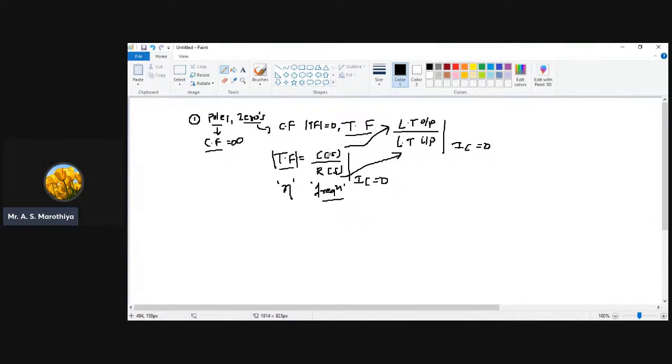And normally to find the zeros, what we need to do is equate the numerator polynomial of the transfer function to zero. In the same way, in order to find the poles of the system, we need to equate the denominator polynomial to zero. That is important. So this is the very first thing that we can collect if we know the transfer function for a given system. Then the second point we determine from the transfer function is the overall system gain, K. What is the overall system gain? That we can also identify through transfer function.